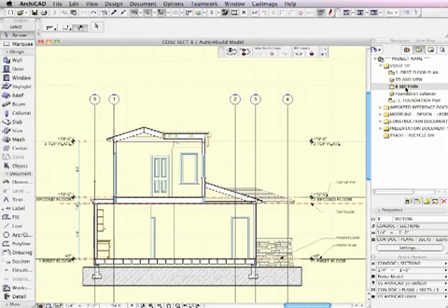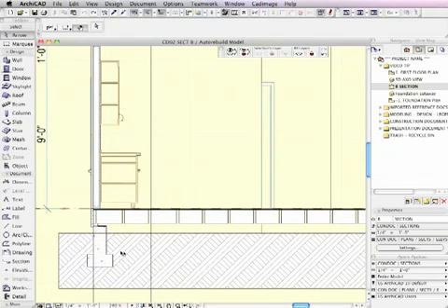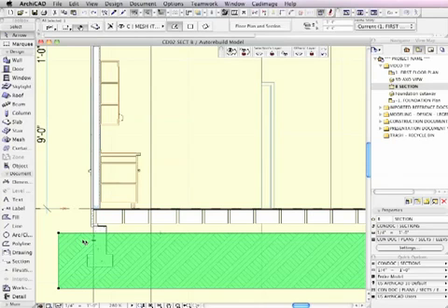The section is starting to be developed. You can see some framing in there and even the foundation stem wall and footing. But I'll point out that in this area there's a problem. There's a line going across the stem wall because the terrain has not been carved out to accommodate it. In addition, we need to create a crawl space underneath the building.